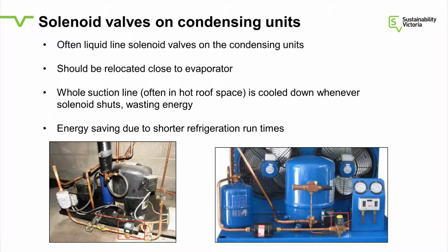And that's done with a solenoid valve. And the way most systems work is it's cold enough, the thermostat turns the solenoid valve off, then the evaporator runs out of refrigerant, the compressor pressure goes down because it's now sucking a lot of nothing, and then the control turns it off on low pressure. And it sits there until the room temperature comes up, solenoid valve opens, liquid goes back in, pressure goes on, and the compressor turns back on. And that cycle repeats itself again and again and again.